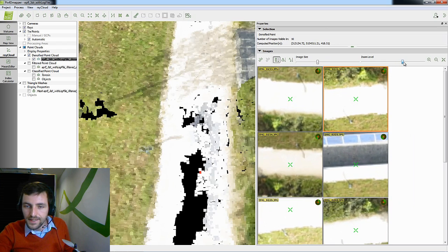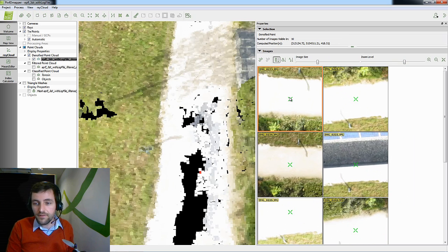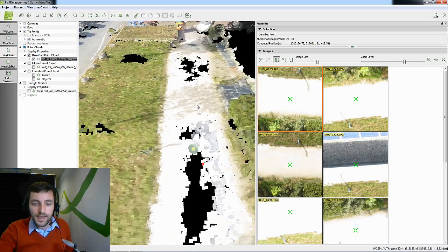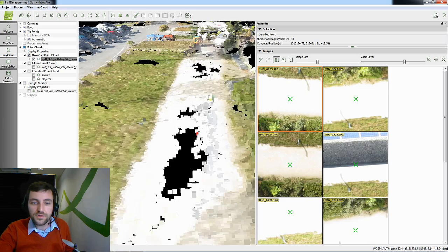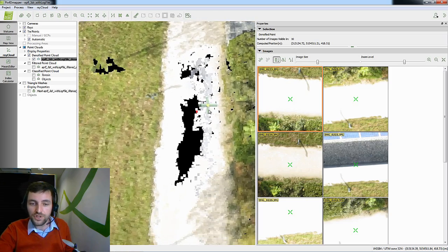And what you can see in the imagery is that the road was very reflective and was overexposed, meaning there was no information about pixels in this area. And because there's no information, this confuses the software and it's not able to compute precise 3D information in it.